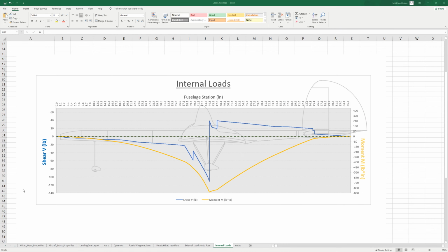So what do we do with the output here of the loads? Well, downstream is stress calculations. We would take the loads we calculated, the M and V, and apply them to regions or cross sections of our structure, and check how overbuilt or underbuilt it is, and how much we need to beef it up to resist those loads to be just strong enough and not too heavy.